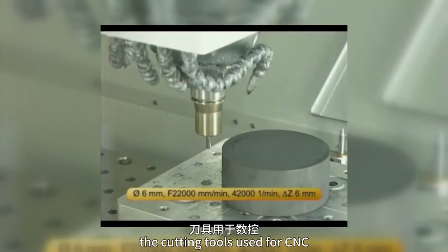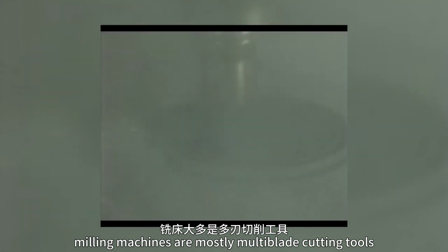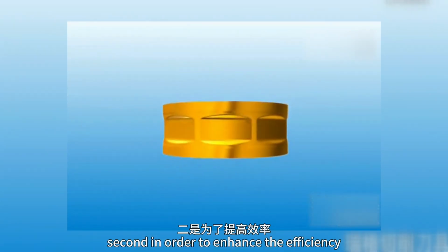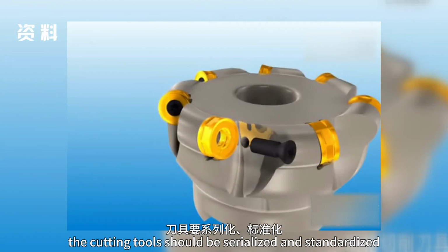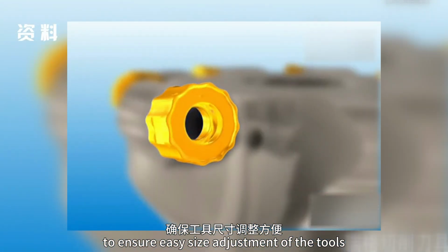First, the cutting tools used for CNC milling machines are mostly multi-blade cutting tools with higher efficiency. Second, in order to enhance the efficiency and shorten the assistance time, the cutting tools should be serialized and standardized to ensure easy size adjustment of the tools.